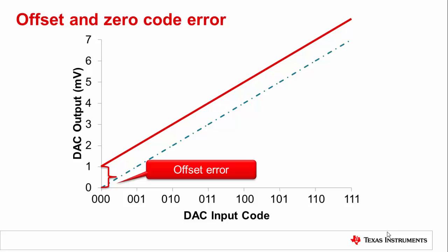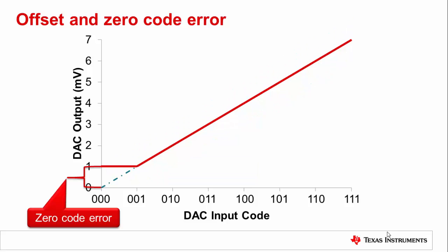It may seem clear that if the transfer function is offset, a zero code will not produce exactly 0 volts at the DAC output. You might guess that instead, it will simply produce the offset term at the output, and you would be almost completely correct for bipolar DACs. For a unipolar output DAC, however, operation near the negative rail is nonlinear, and we will see an additional offset from the expected linear transfer function value.